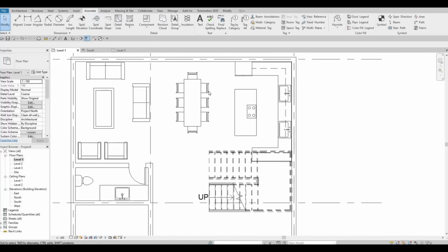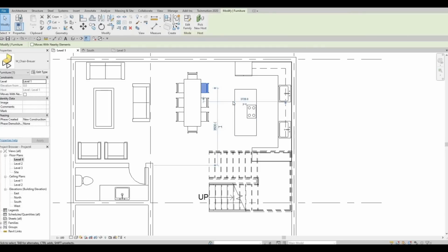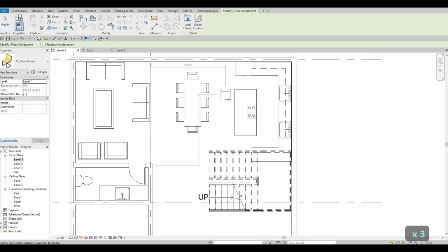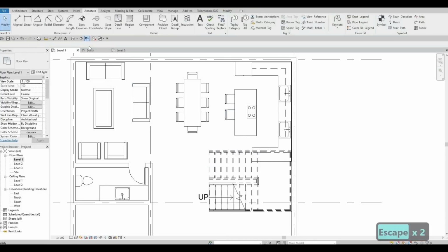And then let's insert some chairs, or we could just use this same chair. So what you can do is click this and type in CS, or this icon. This is the create similar. And once you type it, as you can see, it activates to create these chairs again. So you could add it. You don't need to look for it on the architecture component tab.